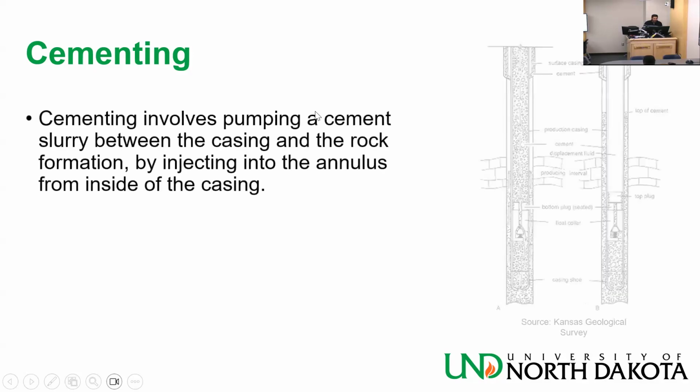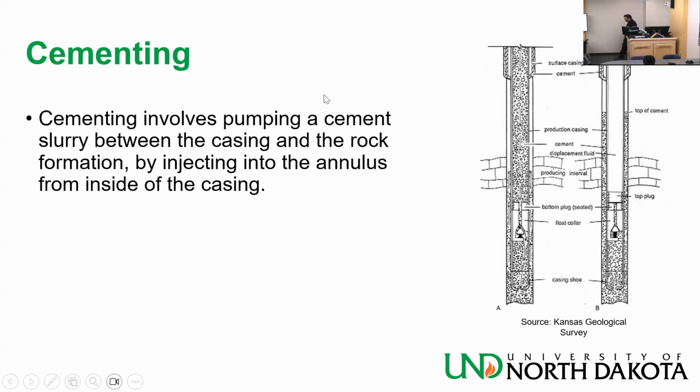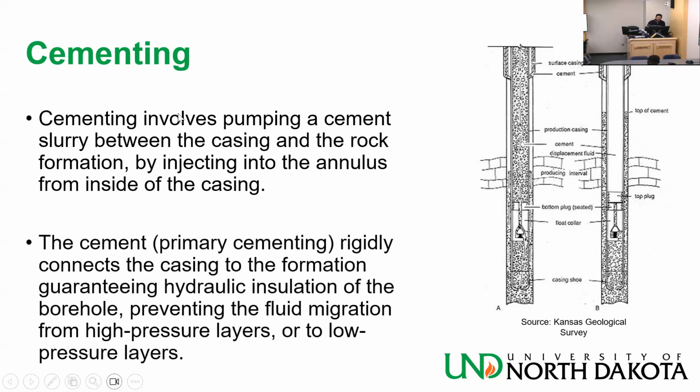So we have been discussing cementing, and we said that a normal cementing job, what you expect to be done when you're on the oil field, you run casing, you pump cement downhole from inside the casing, and you get it through the annulus, and you let it basically settle. That is primary cementing. Secondary cementing is mostly for remedial purposes, like you are doing it to fix cementing jobs that are not good so far, and stuff like this.